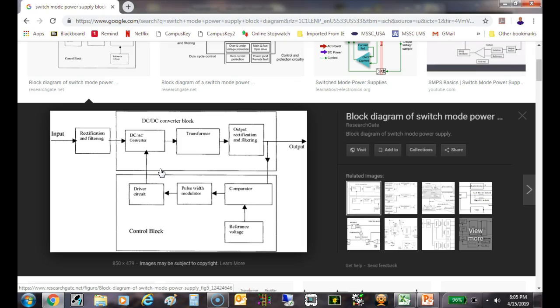Just about all your switch mode power supplies are going to be sealed in a block. So if this guy right here goes out, you're going to do what? You've got to buy a new one. But look, you've got these little old things we call bricks. Those are switch mode power supplies. Look how small those things are. Look at them real close and see how much current they put out for that size. Most of them put out over half an amp.